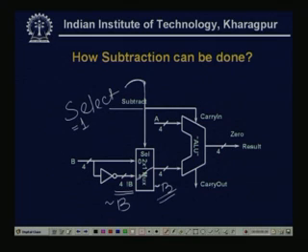So, this is my arithmetic logic unit. Say it is a subtraction. So, here the 4-bit a values will go, and the 4-bit b complemented values, and if the arithmetic unit is selected by this select line or that carry, then the subtraction will be done at the output of this particular ALU, and here is the carry out. So, in this way we can see the subtraction individually.